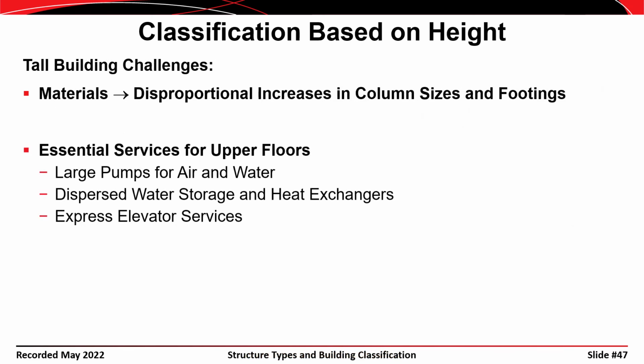Okay, tall buildings represent challenges in general. First of all, the materials tend to be of a higher strength. You might end up with a higher strength concrete. The columns tend to be larger to resist the extra gravity loads, and the footings and the foundation tend to be larger. Additionally, larger pumps need to be installed in basements of the building to push water to the top.